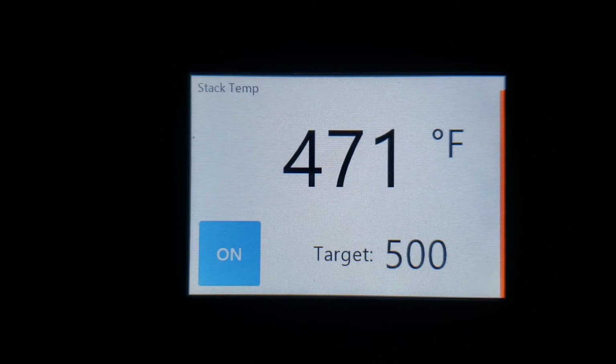And one nice thing about that indicator is, you've got a lot going on in your shack, you're not going to be able to hear that blower whether it's running fast or slow. So when you look at the screen and you see that you're running at a low temp and your blower's running at maximum speed, that's a dead giveaway that you better start getting ready to shut this thing down and top off your stove.